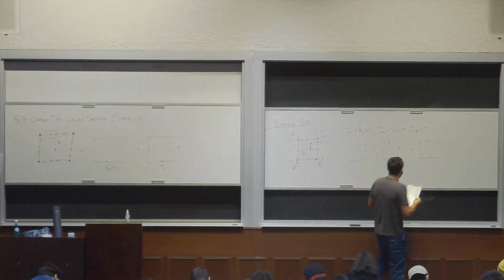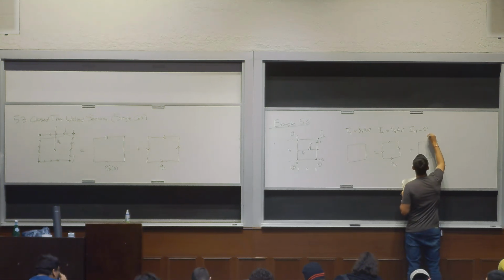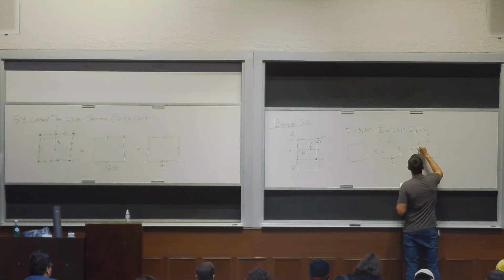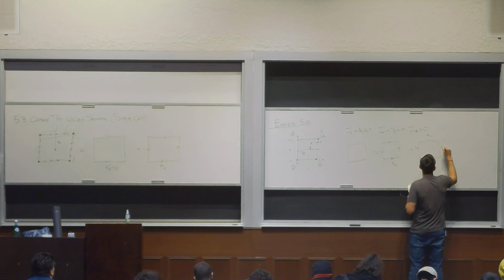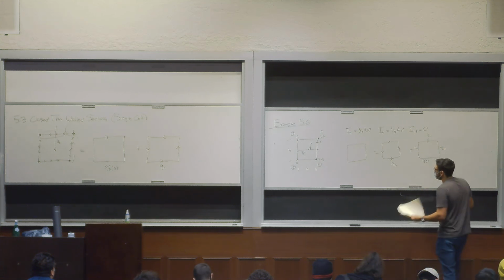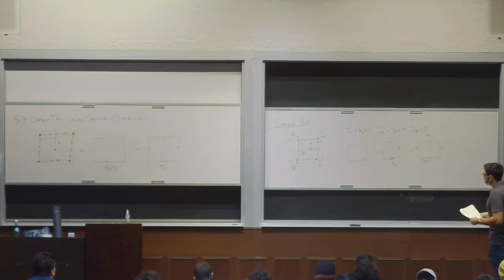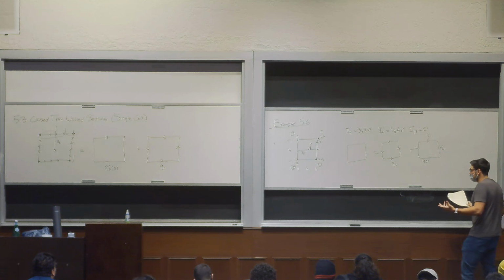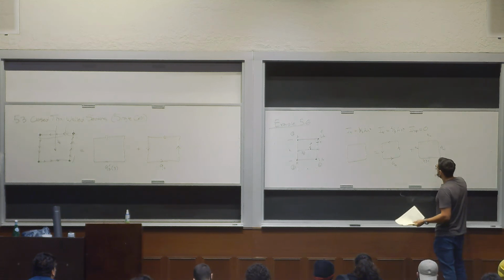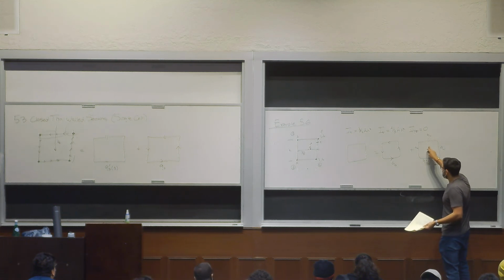So these are the Q's: Q12, Q23, Q34, and Q41. We're going to have to solve for 4 different shear flows. The good thing about these thin spar web sections is that whenever you make the cut, this whole thing goes to 0, because these areas are negligible. So that's good.